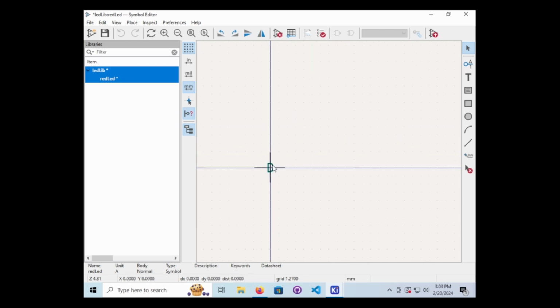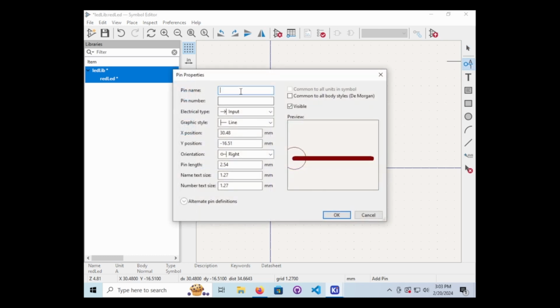So it automatically put a D symbol down for you. I'm assuming we can select and move that. Alright. And usually, this looks like pin. Yep. So we're going to add our pins. And we're going to do one. So, pin number, let's see, pin name. So the pin number is the important one. The pin numbers, you always want pin 1 and pin 2. Pin name is where you could do like, usually like a negative or something else. The easiest thing is just the same.